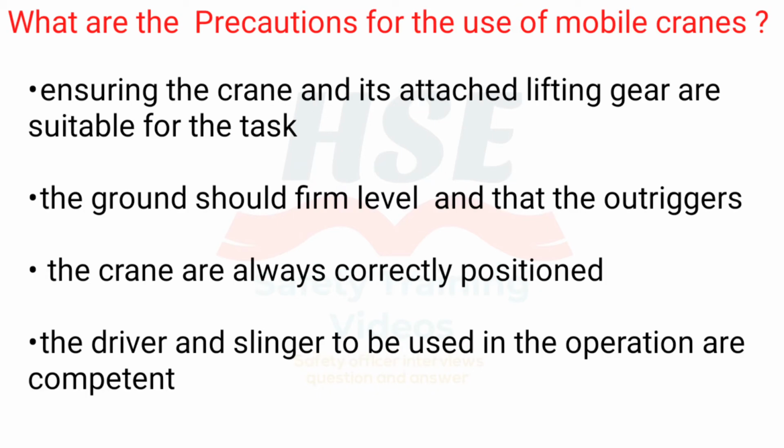What are the precautions for the use of mobile cranes? Ensuring the crane and its attached lifting gear are suitable for the task. The ground should be firm and level and that the outriggers of the crane are always correctly positioned.